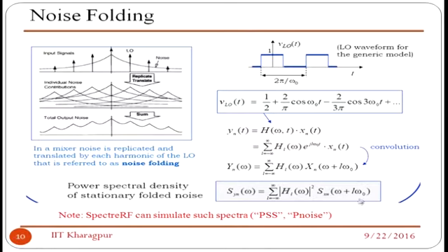And that noise power is coming from your Cadence SpectreRF. So, when you talk about the phase noise or PSS, then actually you are calculating this, right? And then you are only considering the odd harmonics because you are considering the square wave. Now, there is a trick which you should know.